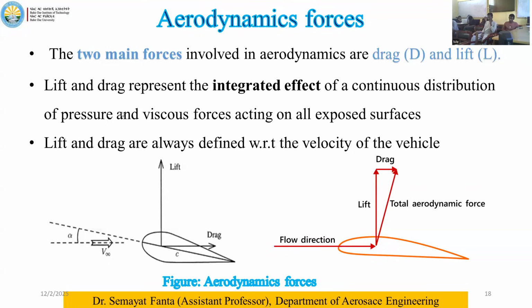Weight is an inertial load, so we cannot say it is an aerodynamic force either. But in general, we call the four of them the four forces of flight. From them, the two aerodynamic forces are drag and lift. So we will see them in detail.